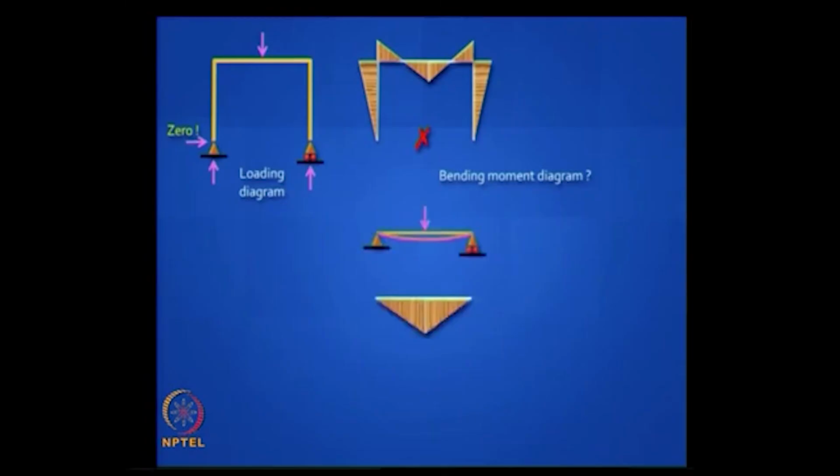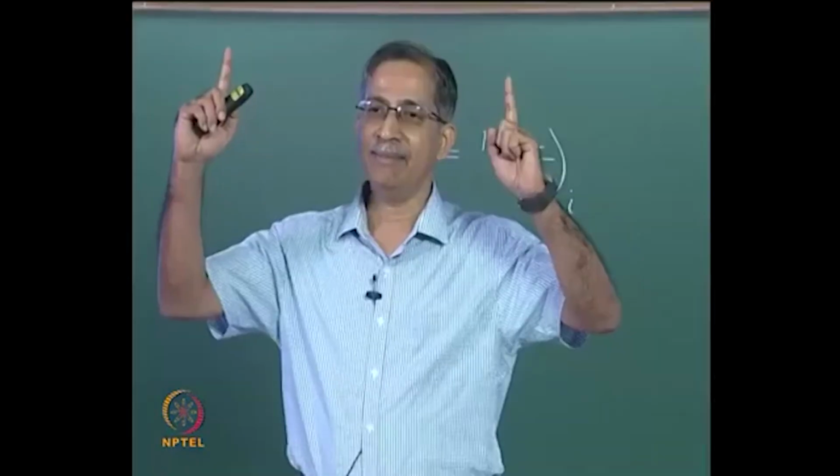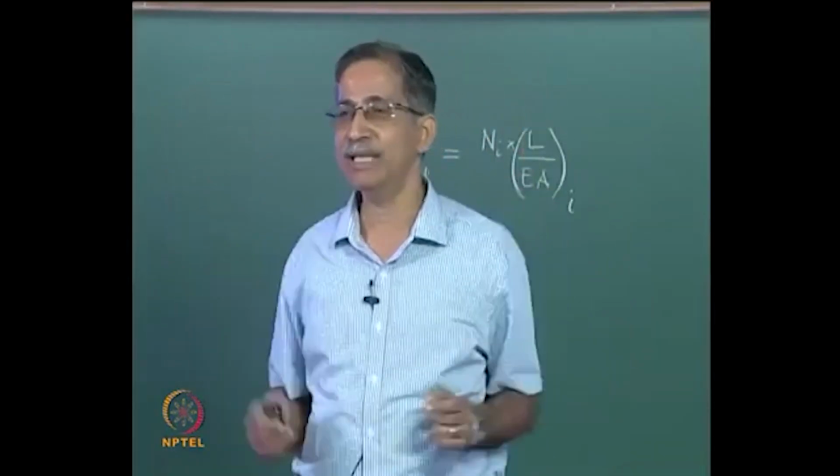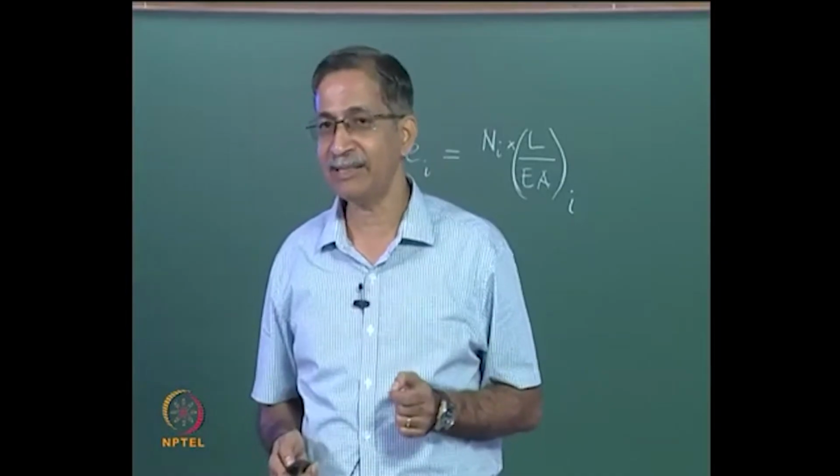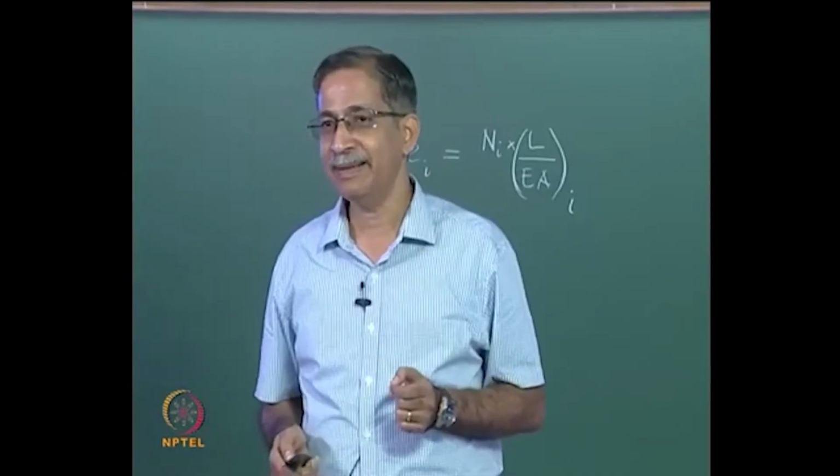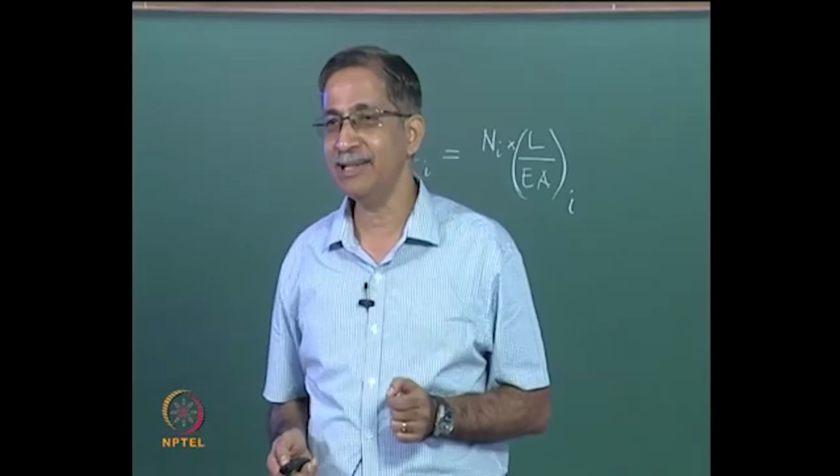So that structure will behave just like a simply supported beam, and the bending moment diagram is just like a simply supported beam. Those two vertical elements are like some legs, some props holding it up together. What about the deflected shape? And that's a challenge, that's a real challenge to draw.